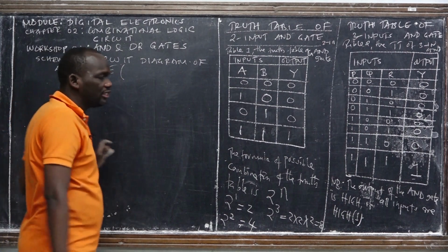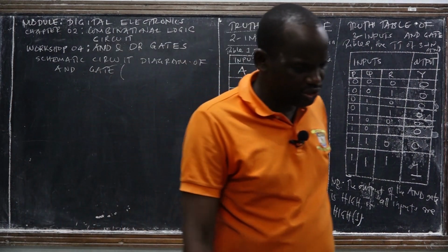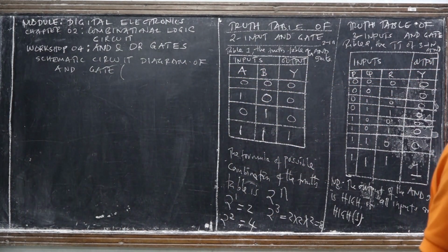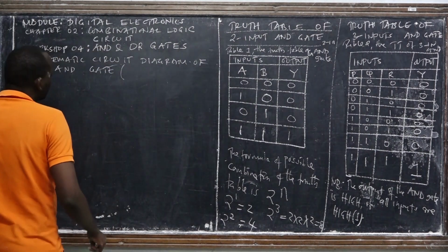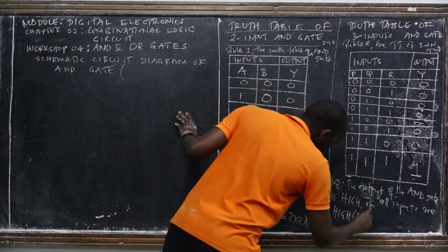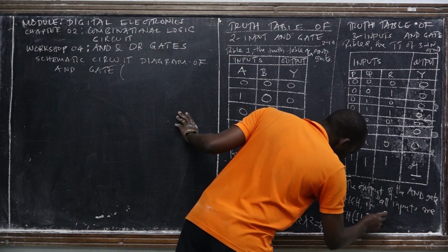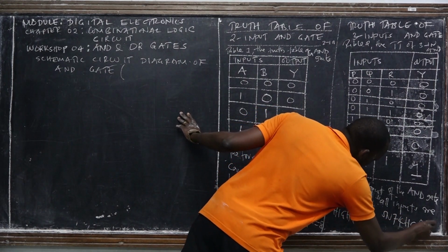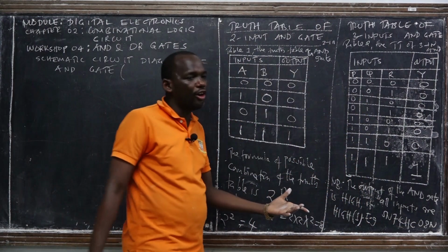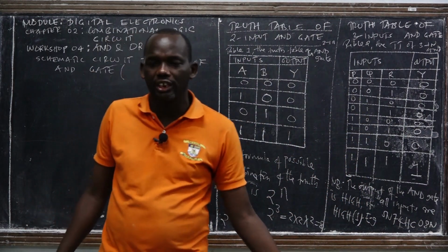So an example of this AND gate, what we used to start with is SN 74. For example, it's SN 74 HC 08N. So 04 is the NOT gate. 08, it's what?